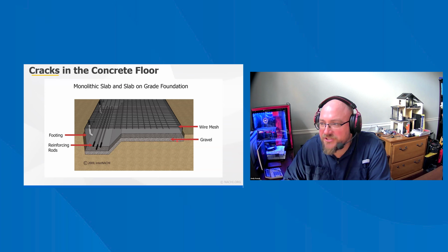Shrinkage or curing cracks generally occur in any continuous length of concrete longer than about 12 feet. As with basement foundations and footings, the local building code does not always require horizontal reinforcement of the thickened edge footing of a monolithic slab on grade. The same applies to a stem wall and independent slab construction.